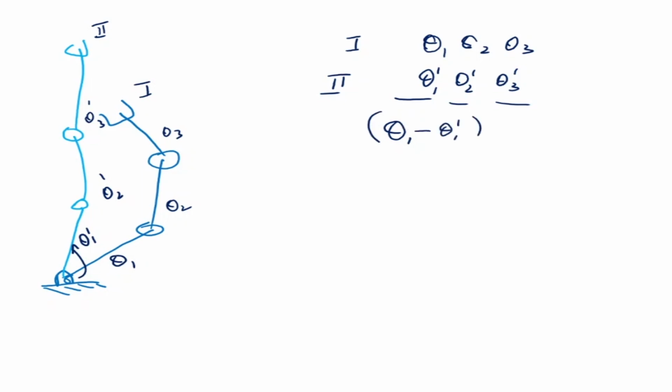So what it will do is move the joint from theta 1 to theta 1 dashed in some time t. Till now, in inverse kinematics, there was no time involved. Now we have to see that in the real world, we have to move the manipulator from one position and orientation to the other. Now it can be done in 2 ways. I could fix a trajectory onto the end effector and say that it has to follow the trajectory like this. So from here to there, it's a trajectory basically.